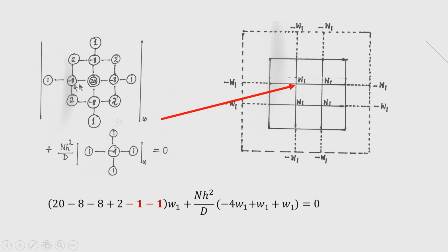Okay. So, this is the stencil for the buckling equation of the plate, that is, you can call it the molecular form. So, if we now place the stencil here, there are two parts: one is for plate bending, that you can see as del 4 W, and this is for the buckling part, that is N square by D. So, now let us first place this.